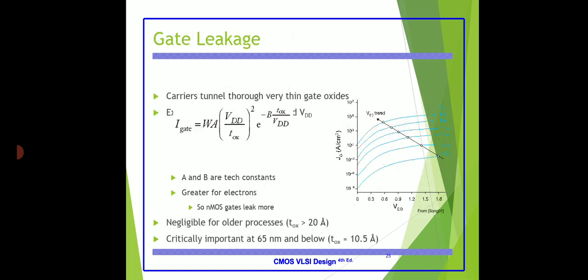So in the gate leakage, the gate and the channel form a capacitor. Here no current can pass through the capacitor ideally, but with the decrease in the oxide thickness between the gate and the channel, electrons tunnel across, which constitutes a gate leakage current.